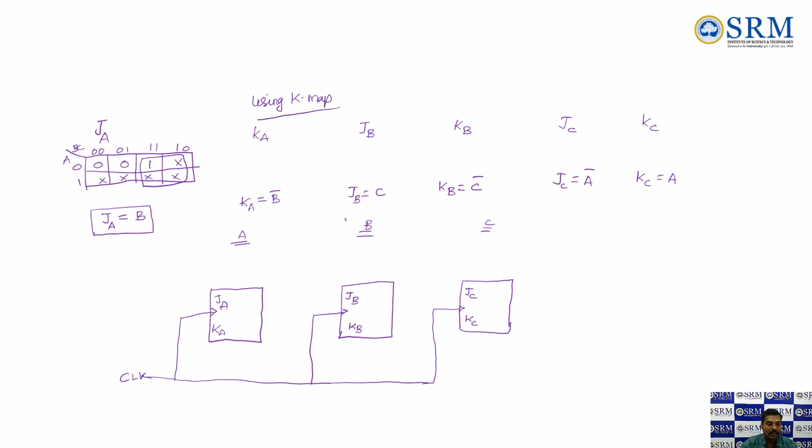Now we have given the clock pulse, so the output will be A, that is QA or A, whatever you want you can use. This is A bar. If this is QA, this is definitely the complement of this output, right? This is B, this is B bar. We use the notation ABC, hence I'm using the same ABC here for your easy understanding. This is C, then this will be C bar, right?